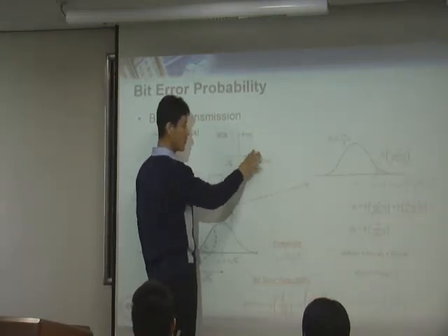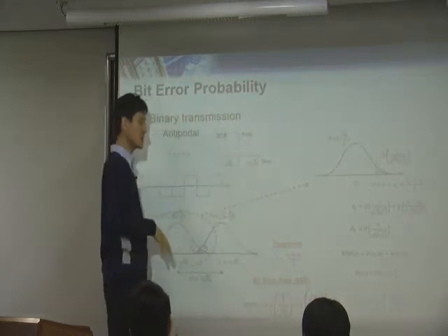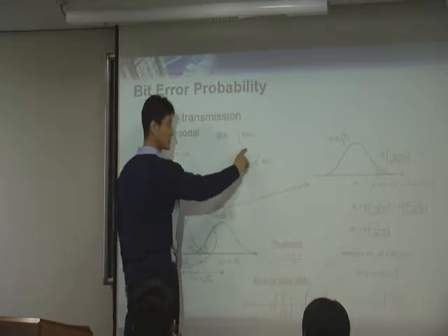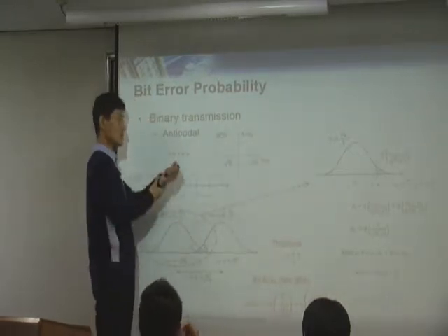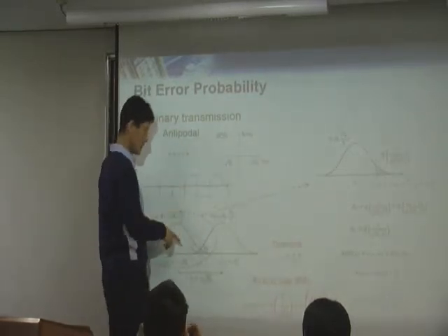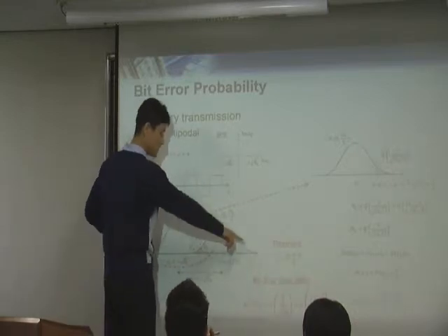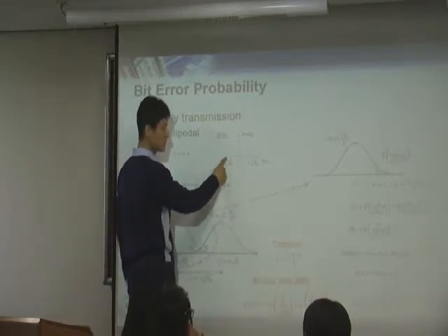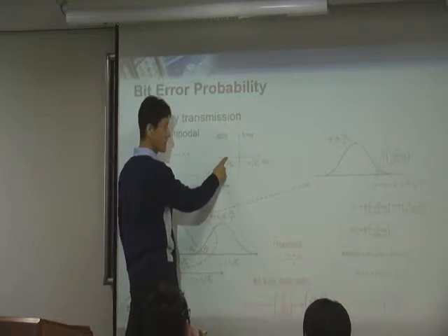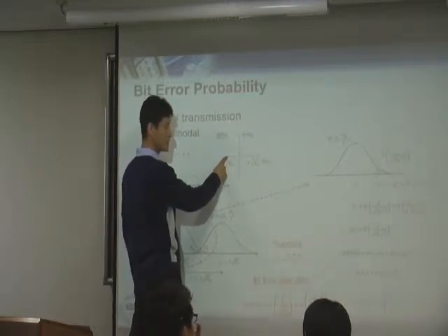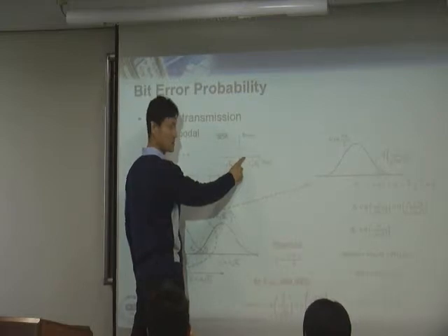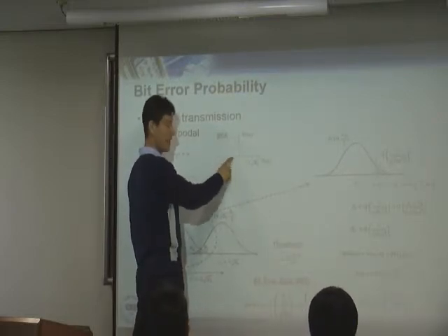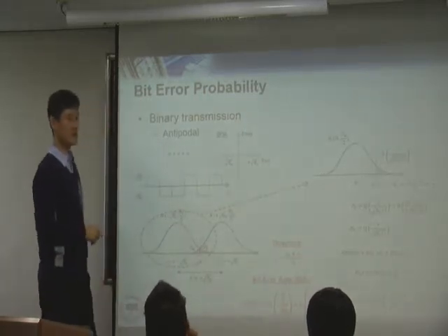So if you think about so many of them and look at the statistics, we see that the error statistics is Gaussian, right? Now you know that the Gaussian has an infinite length tail. So what that means is if you transmit this one, then it may be received as this symbol with some low probability. That happens to be an error.